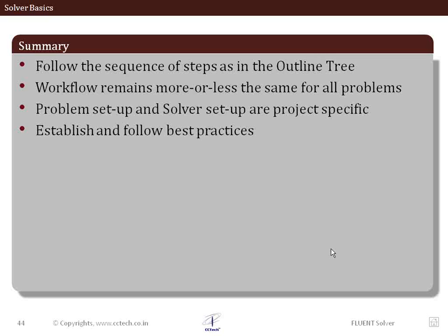So overall, if you have a look at the approach that we have to follow for solving a CFD problem, some fundamentals are very helpful. The basics that we have to follow are as described in the outline tree. We set up the problem, we set up the solution parameters, and we start off with a mesh. We start off with an initialization. We proceed either in time or through some iterative scheme until we achieve convergence.